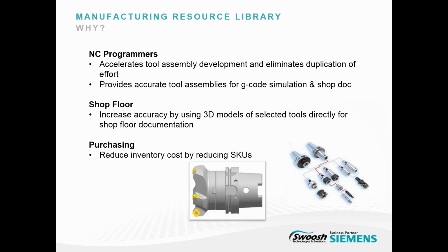Why would anybody want to use MRL? So from a programmer perspective, it really does help you develop your tool assembly quicker. It also eliminates the duplication of effort. Let me give you an example of that. If I gave 5 different programmers the same job to program, chances are I'm going to get 5 different programs and probably 5 different tool lists. That will not happen if you have this system and you have predefined tooling done by the administrator.